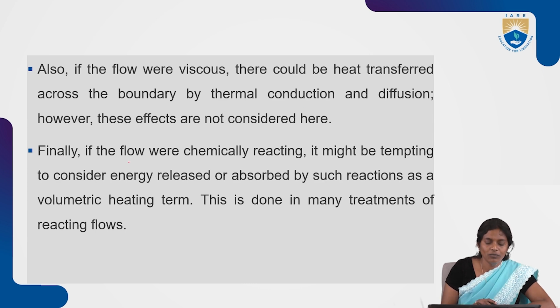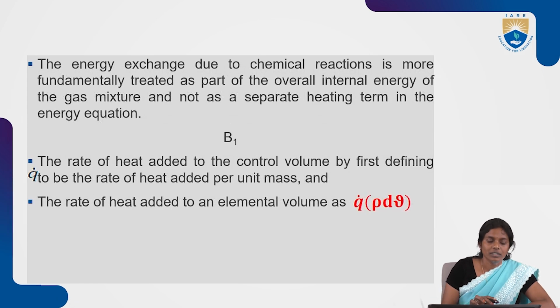Finally, if the flow were chemically reacting, it might be tempting to treat the energy released or absorbed by such reactions as a volumetric heating term. This treatment can be done for many reacting flows. However, the energy exchange due to chemical reaction is more fundamentally treated as part of the overall internal energy of the gas mixture, not as a separate heating term in the energy equation.